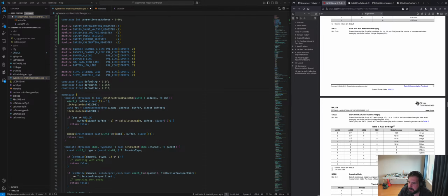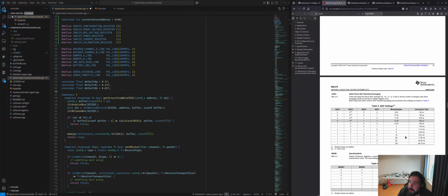So I'm thinking we do this 32 sample averaging. Basically, the chip will monitor 17 milliseconds of power and compute the average amount of power that moved through it during that window, just to lower the overall load. I mean, this is a little pokey 8-bit microcontroller after all.